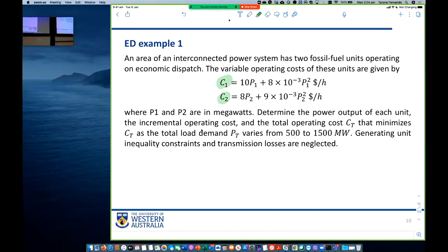So we have a second equation. So those two equations are linear. Well, with two equations and two unknowns, we can solve for the unknowns, P1 and P2. So that solution for P1 and P2 is the dispatch, is how much we're going to assign each of those generators to generate. And that will be the least cost of meeting the demand using the two generators.